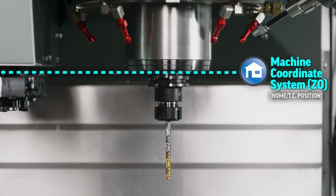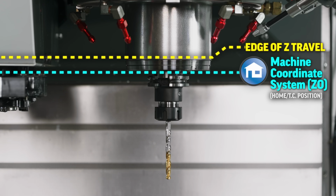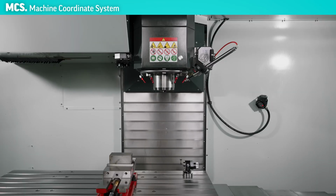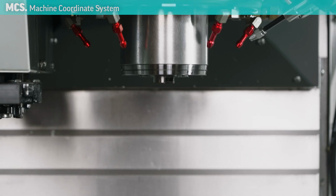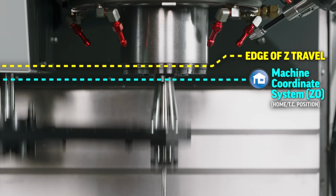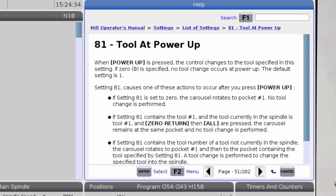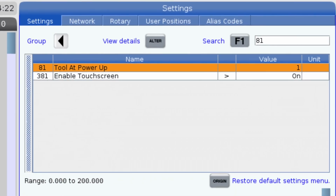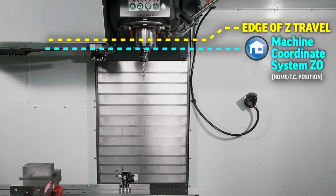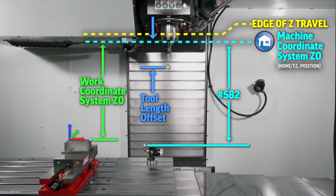Now, contrary to popular belief, our Z home position is not at the edge of our Z travel. When we press the power up key on this Haas mill, the spindle head will travel up and find the edge of our Z travel before moving back down to our tool change position before putting tool 1 in the spindle. Setting 81 defines what tool we want in the spindle after power up. It is this tool change position that our Haas mill uses as our home position, our datum from which all other Z tool and work offsets are referenced from, our machine coordinate system.